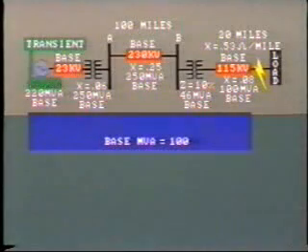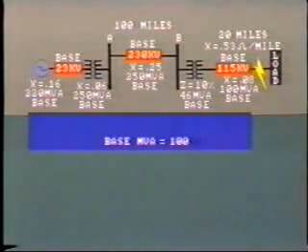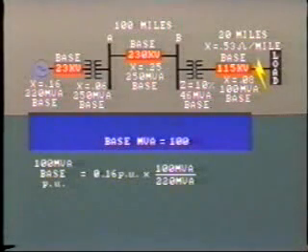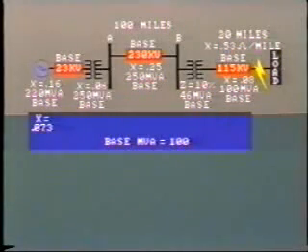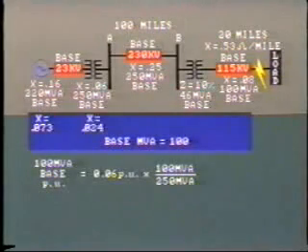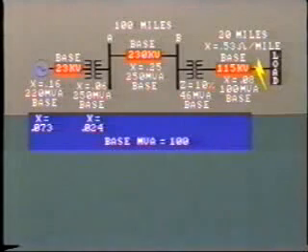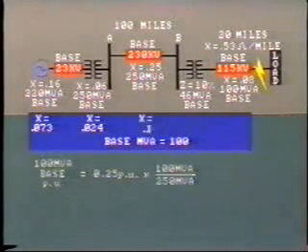Let's do this. The generator transient reactance is given as 0.16 per unit. The term transient refers to the changing conditions which occur initially during a fault. The generator is rated at 220 MVA, so in order to bring the reactance to our common 100 MVA base, we must multiply by 100 and divide by 220. The corrected value is 0.073 per unit. Mark this on the diagram. Similarly, the step-up transformer reactance, 6%, must be reduced from 250 MVA to 100 MVA base. This gives us 0.024 per unit reactance. The 230 kV transmission line indicates per unit reactance of 0.25 on a 250 MVA base. This converts to 0.1 on the 100 MVA base.